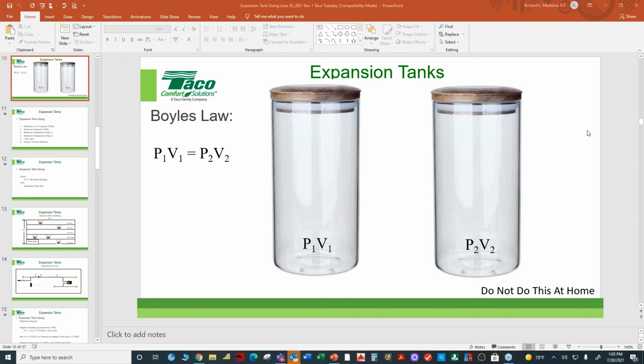Awesome. We're just about at the end of our time period. Do we have one last question, Brett, and then we'll have to wrap it up? For high efficiency boiler systems that use lower water temperatures, should you use 180 or 150? You should use the design temperature of your boiler system. If your boiler system has a temperature of 150 degrees, you should use that as your maximum temperature. If there's a possibility it can go higher, if something runs away, then use the higher one. You know what I mean?